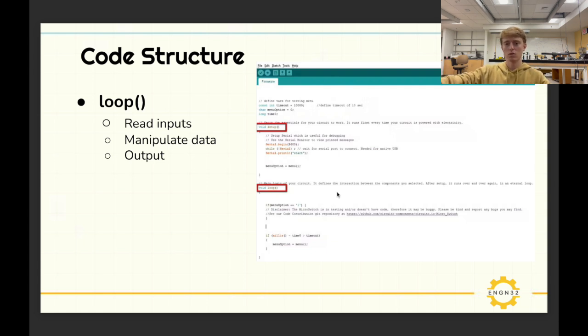So I will write to a different pin, for example. Okay, that might be something that you do. And that's called polling, where I just read inputs over and over again, and then I go manipulate an output based on whatever my code specifies, okay? But the main point here is this is going to be called over and over again. That's why it's called loop.